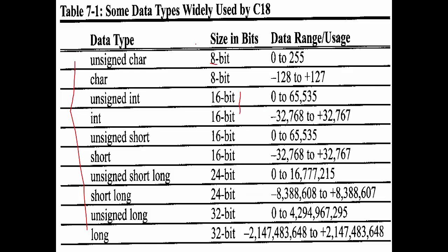So why is this data type needed? We have only a small memory space in a PIC microcontroller or any other microcontroller. The memory is along with the processor, embedded into a single chip, so the available memory space in a controller is very small. If the usage of memory space is effective, then only the space will be utilized for many applications. Otherwise, if I am assigning an integer for 8-bit data, I am unnecessarily wasting memory locations. So that is the reason the data type must be assigned properly.